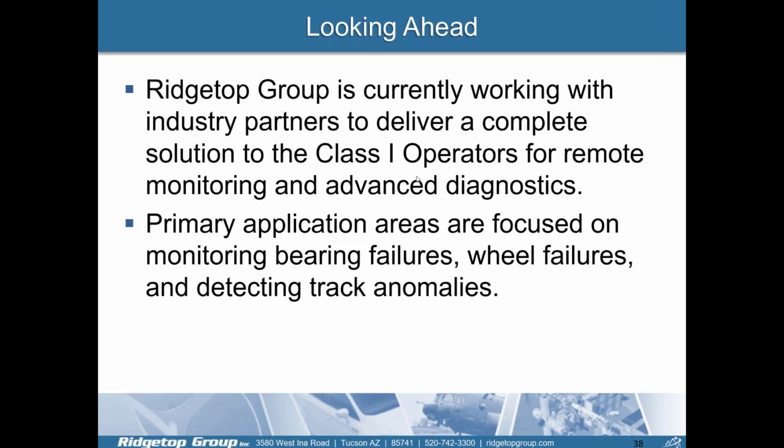Also, with hot box detectors and WILD systems, those are two different types of sensing devices. The hot box detector is a wayside detection system that is spread out every 25 miles or so, at least here in the U.S. on the Class 1 tracks. And they monitor the temperature of the bearing system as the train is going over. But on that note, RotoSense is able to do much more frequent measurements as opposed to every 25 miles. So you'll be able to see that bearing temperature anytime you want to.